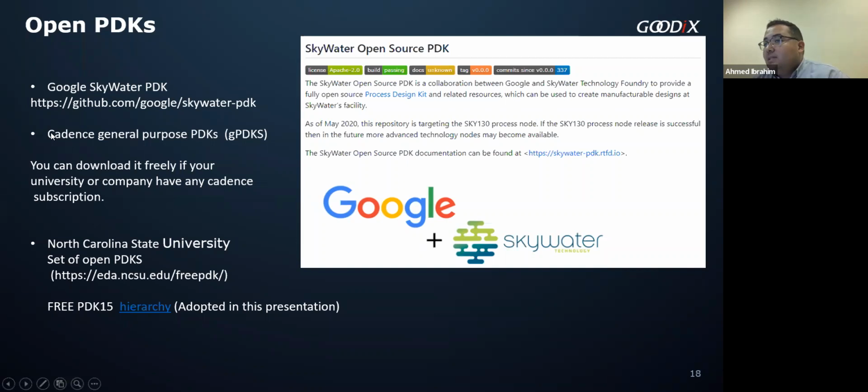Cadence provides high quality PDKs called GPDKs. I think for 180, 45, and they have new advanced PDKs that imitate FinFET technologies. So you can download it freely. If your university or company has a subscription, you can just download it from the Cadence support site. The North Carolina State University set of open PDKs, this is the one that I adopted and showed you in this presentation.